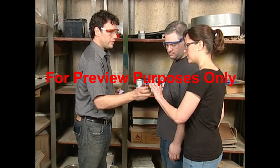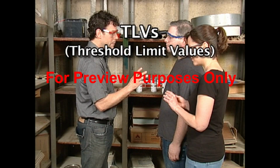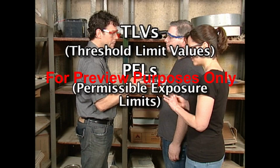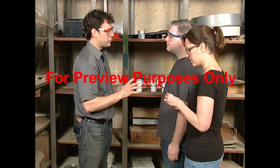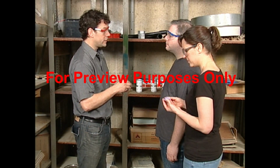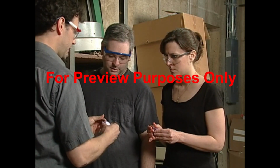Section 8 of the Safety Data Sheet will also list any TLVs, threshold limit values, PELs, permissible exposure limits, or other established exposure guidelines for the material or its hazardous ingredients. This information is used by your employer to determine the engineering controls and personal protection that is appropriate for the work you are doing.